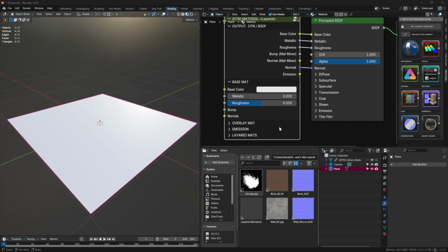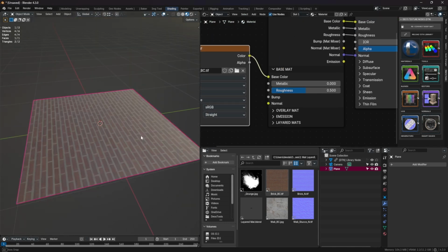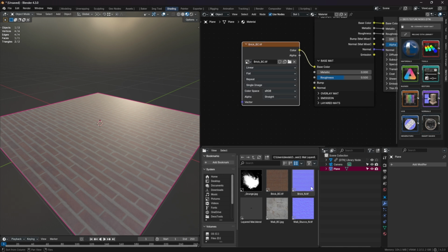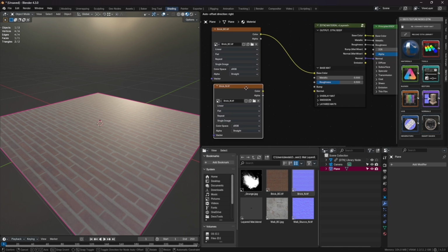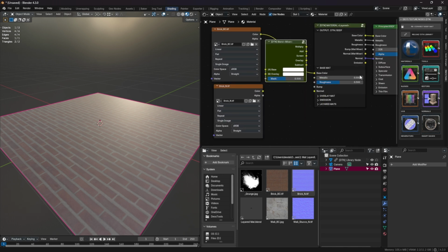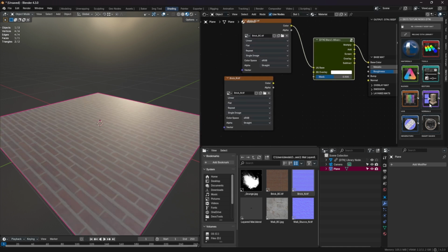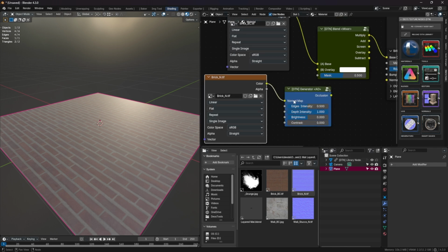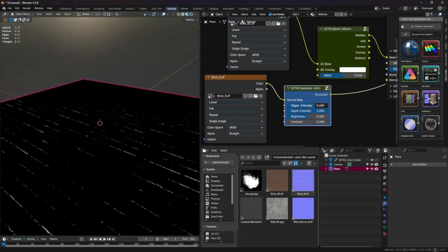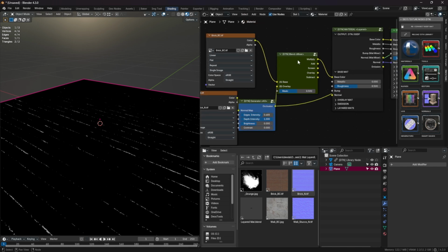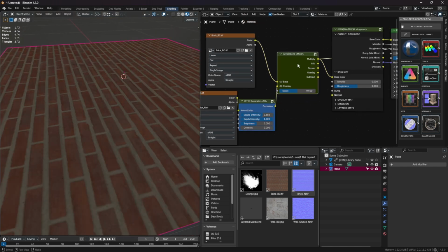This layered material is divided into base and overlay, allowing you to use two different materials. Also, you can use blend modes to mix two texture slots, and you will get the most common outputs to mix. Also, you can use from generators the AO node that allows you to use a normal map to create an ambient occlusion. But remember to use the non-color space in normal maps.